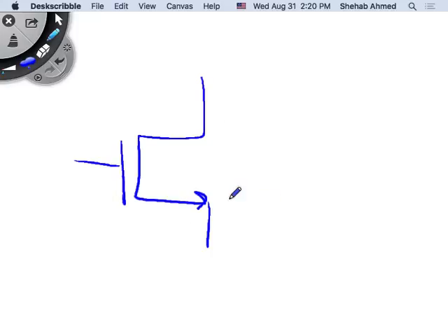We will not care later if it's a BJT, MOSFET, or whatever, because for us it's a switch, right? If I tell you it's a BJT or tell you it's a MOSFET, then maybe it will change the way you calculate losses. But I will draw them all the same way. I will draw them such that this is the direction of current flow. So the arrow will point to the way that current is flowing. MOSFETs are drawn in a different way. BJT is drawn in a different way. But I will typically just utilize this symbol for a switch in our case.